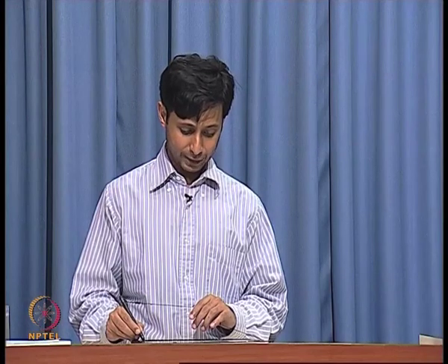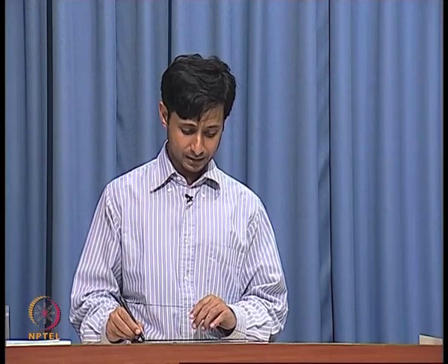Then we solved the equations for the transmission line. We took a special case when I have only got inductance and capacitance. This is the lossless situation. The lossy situation is just a little worse than this. Okay. That also we can solve. Unfortunately, we can solve that only when we talk about sinusoids.